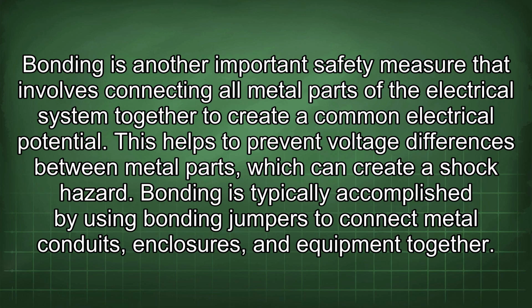This helps to prevent voltage differences between metal parts, which can create a shock hazard. Bonding is typically accomplished by using bonding jumpers to connect metal conduits, enclosures, and equipment together.